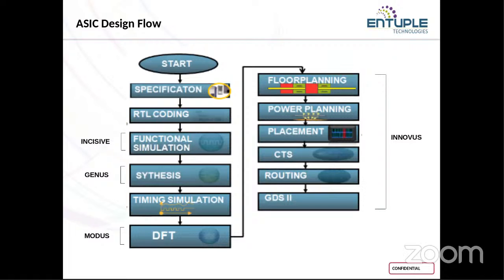Once you have verified the results, if the result is satisfactory, then you will go for your synthesis stage, where you will convert your RTL code into a gate level netlist file. Whatever RTL code we have written is understandable by the user. To get machine understandable language, we convert that RTL code into a gate level netlist file by using your technology node. The technology node basically represents under which nanometer technology you are working on your design.